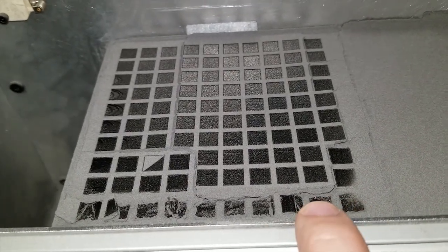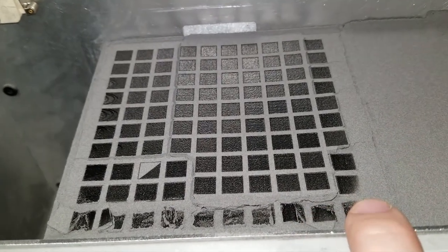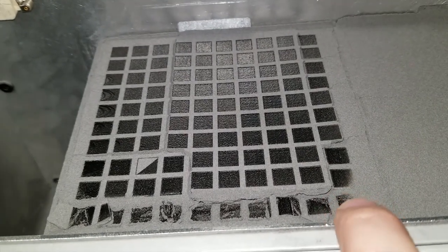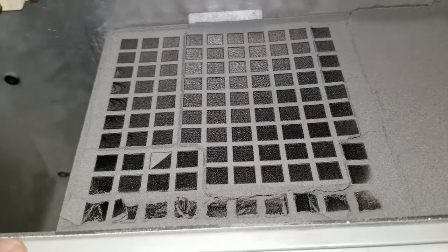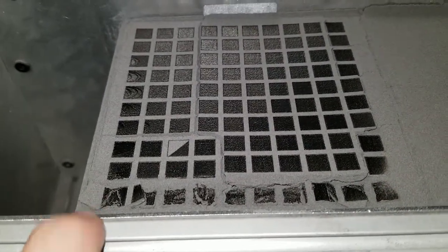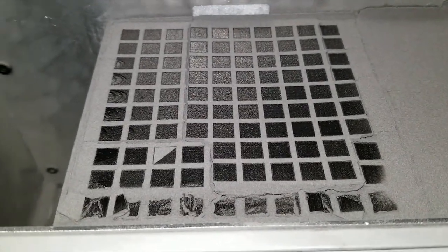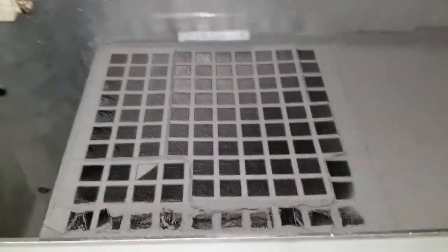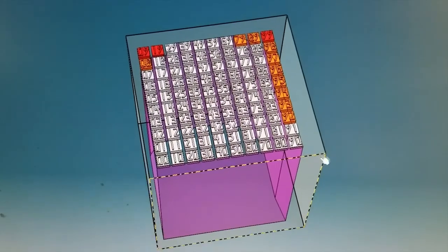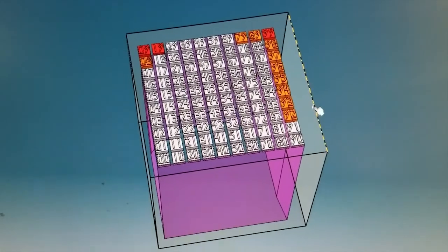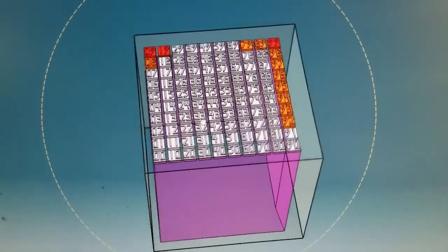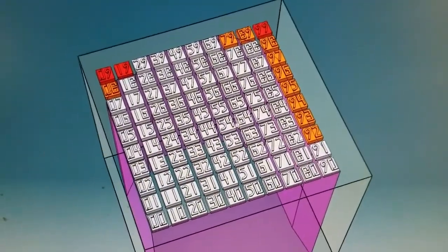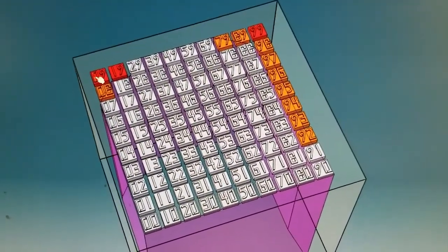If I fix my shadow issue here, or wherever it's blocking my laser light, and I avoid these two squares and this corner here, I should theoretically have a full range of sintering action for this thing. So after examining all of the pieces that came out of the bed, I decided to go back to my original parametric model and identify all the areas that had problems.